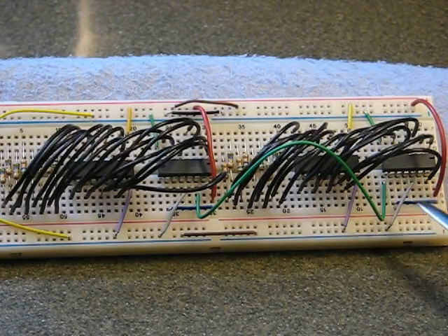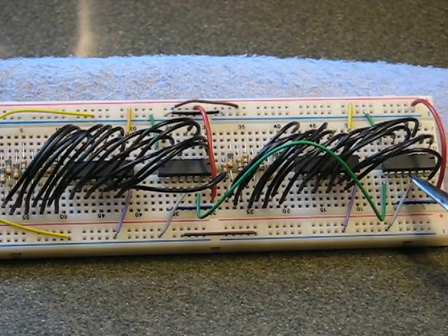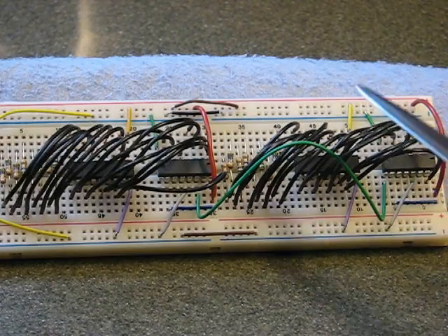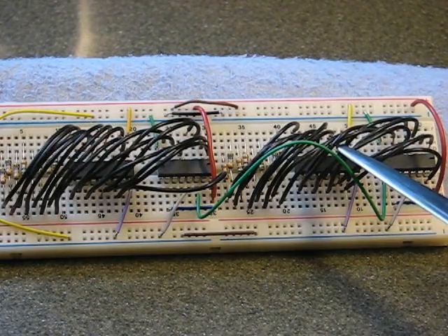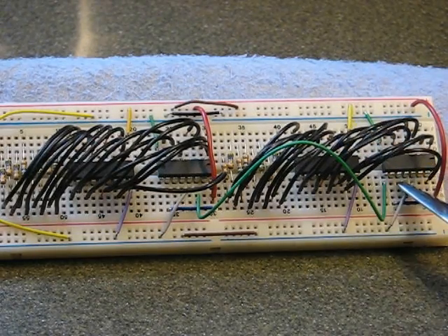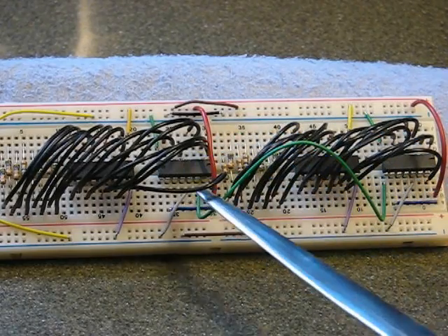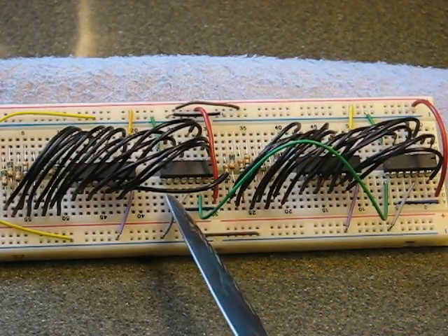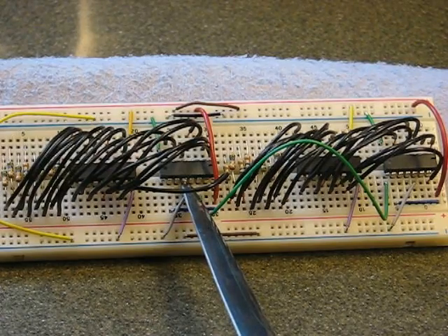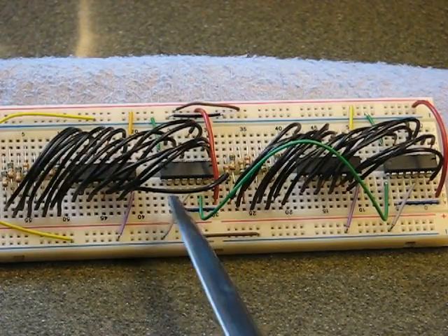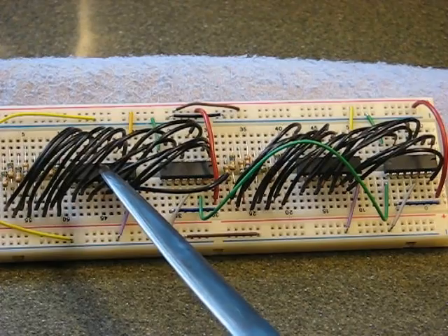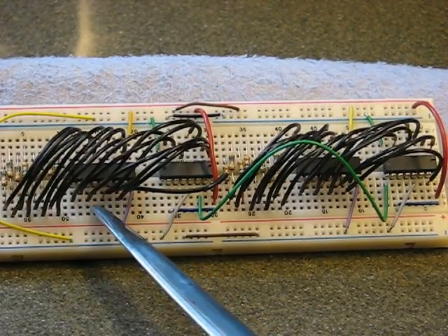So what really happens here is I have 2 bytes coming into this shift register. It sends 1 byte to here for 8 LEDs, and it sends the next byte downstream here to another shift register. This shift register sends its 8 bits to another transistor array, which powers 8 more LEDs.